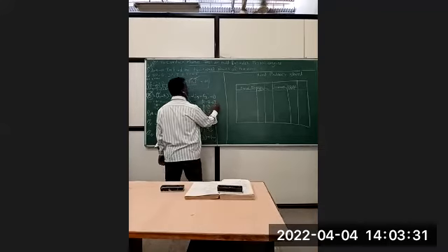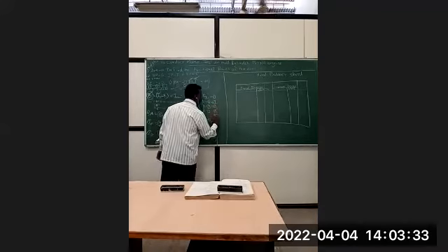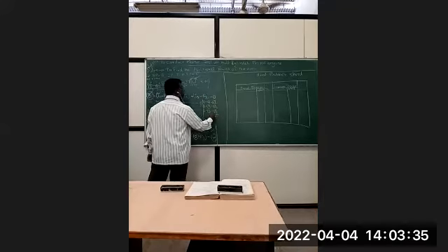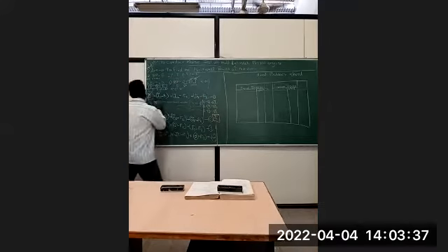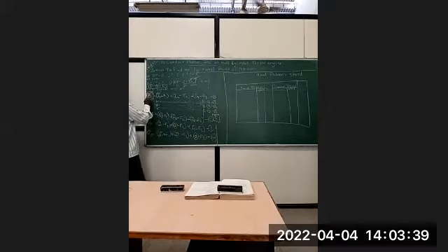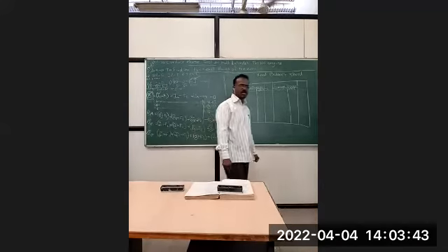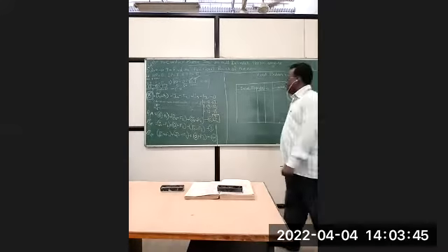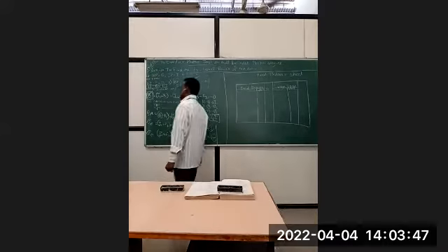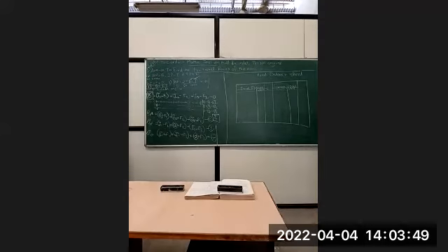But we said that I1 plus I2 plus I3 is equal to I. And now we know what is I, we know what is B. That is, the total brake power and the total indicated power of the engine. I minus B we found to be equal to the frictional power of the engine. So this is how we find the frictional power of the engine.